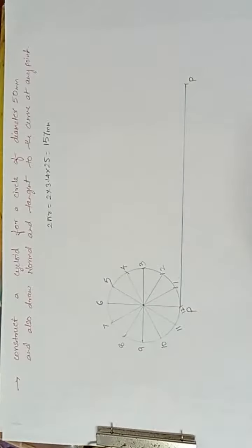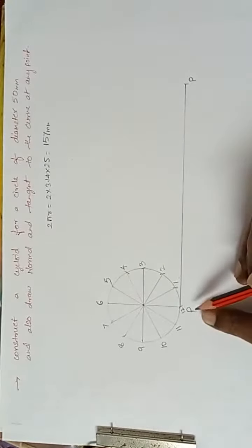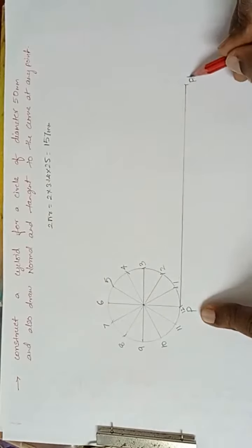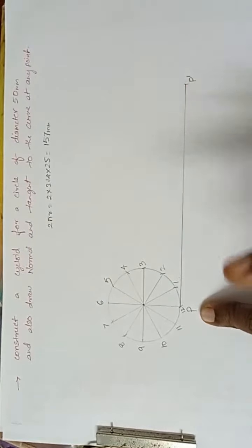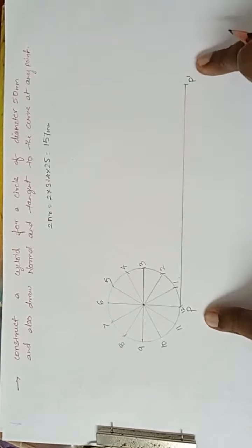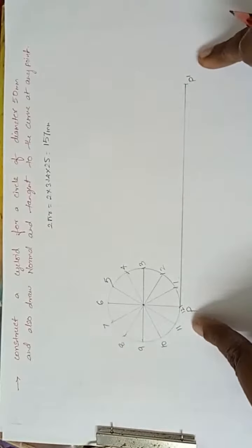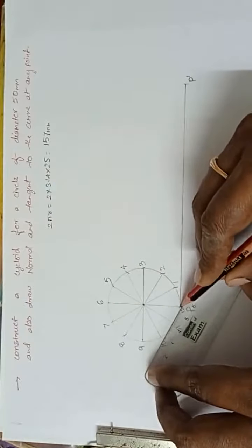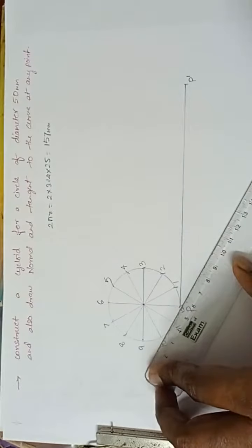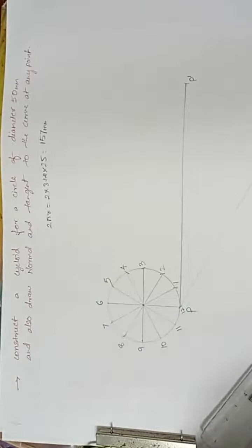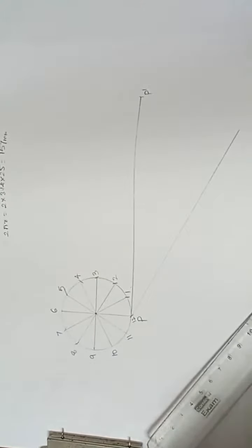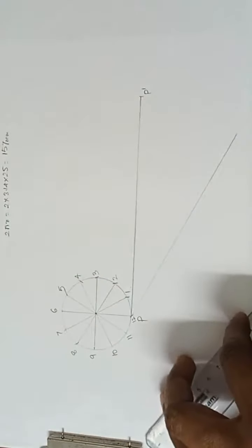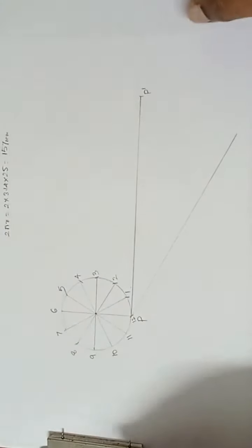Up to 12. Now this is P and this is P dash, I'll name them, just making a difference. P dash is the circumference of a circle. Now again, I'll divide this P dash into 12 equal parts. How to divide? We know the line dividing method, the acute angle line. I'll adjust this somewhat upward. Now let me complete.